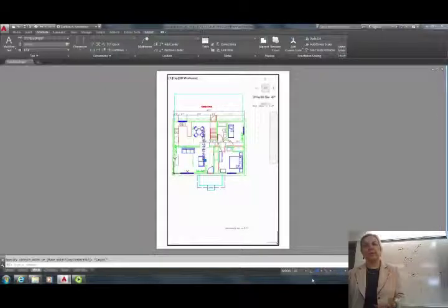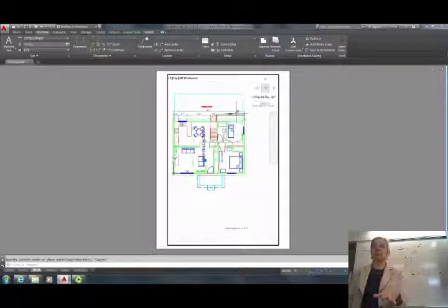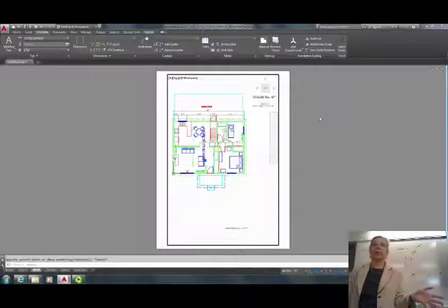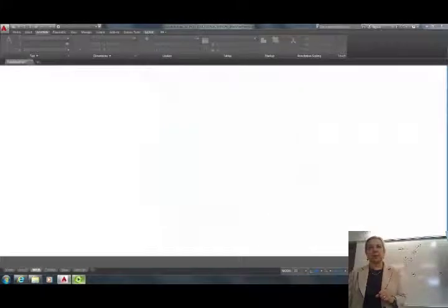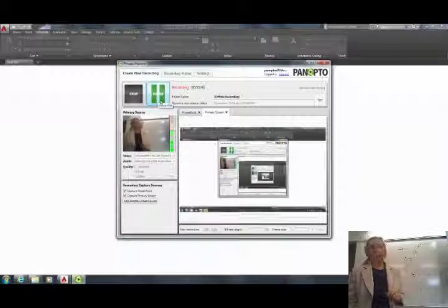So for the final project, I will look that your fonts for texts and dimensions are the same and that the heights are the same. But whether you'll go and try this annotative, we'll watch it, and he shows you everything, how to set it up. Whether you go one way or the other, I will be looking that they are 1/16 of an inch on small sheets. And then in A1 size, they should be bigger. Okay, so let's give it a try on our drawing, but at the same time we will also watch the video based on our